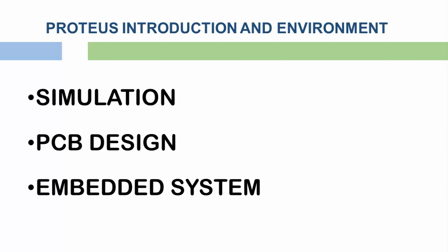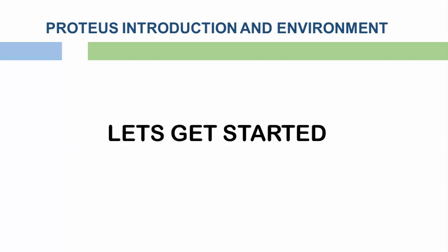Thirdly, PROTEUS is also used for designing or testing programming code for microcontrollers, for instance Arduino code, a PIC microcontroller, or 8051, and so on and so forth. PROTEUS allows you to test your code in simulation, and once you are sure that you are getting perfect output, then you can burn it to the microcontroller and test it on real hardware. So let's open the PROTEUS environment to see what tools are available for us.